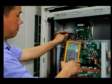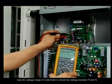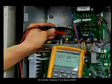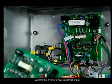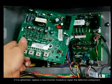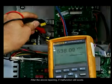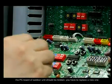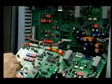Step 2. Use the DC voltage range of the multimeter to check if the voltage between P and N of the inverter module is about 540 volts. Confirm whether the inverter circuit is normal or not. If it is abnormal, replace with a new inverter module or repair the defective component. After the above repairing, if the malfunction still exists, the PC board of the outdoor unit should be broken. You have to replace a new one.